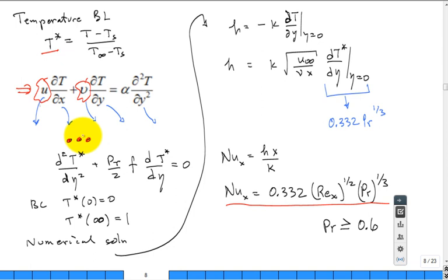But you basically take that PDE, transform it into an ODE. You need the solution to the previous ordinary differential equation, and you have this Prandtl over 2 grouping of terms. This one you take a look at, it's second order in this transformed eta.